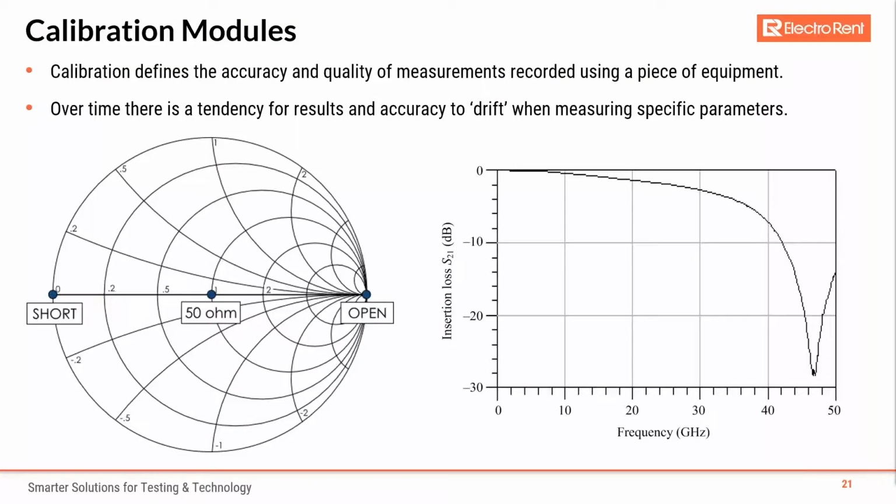Calibration modules. The goal of calibration is to minimize any measurement uncertainty by ensuring the accuracy of test equipment. Calibration quantifies and controls errors or uncertainties within measurement processes to an acceptable level. In the case of VNAs, they are usually already calibrated from the factory. When adding cables or a transmission line, the phase and length of that external attachment must be calibrated out to its end.